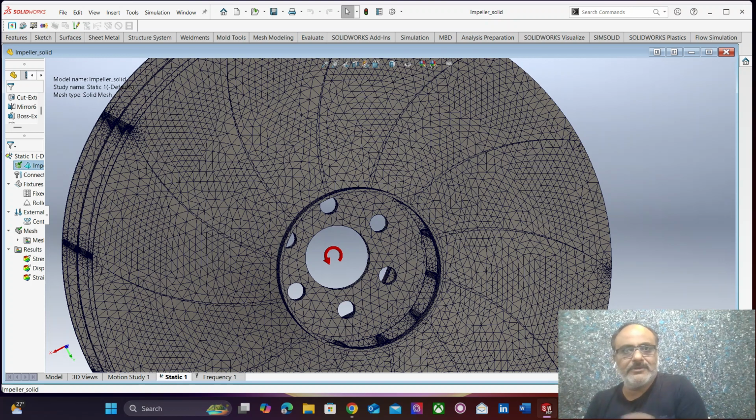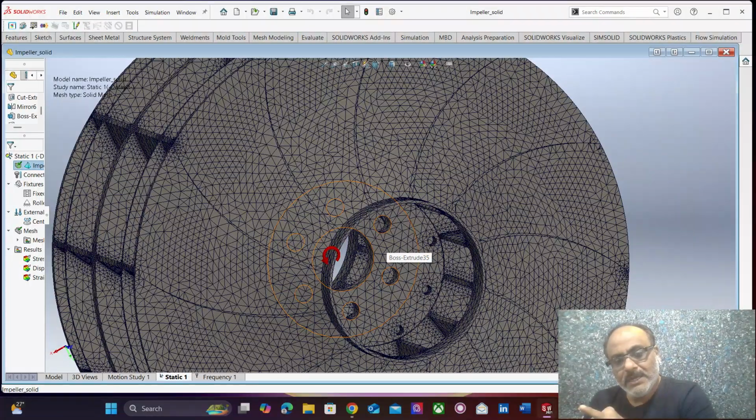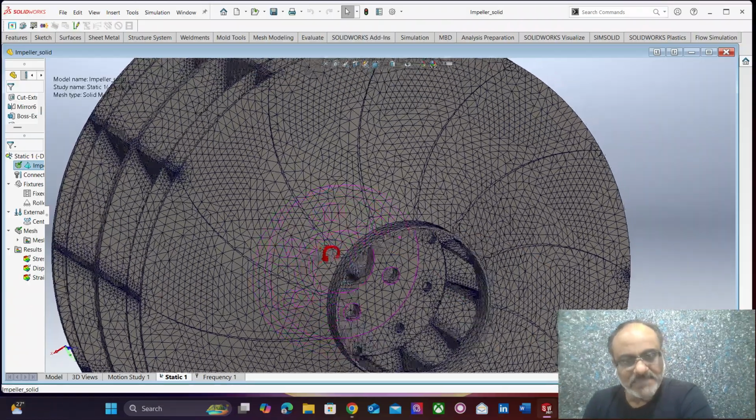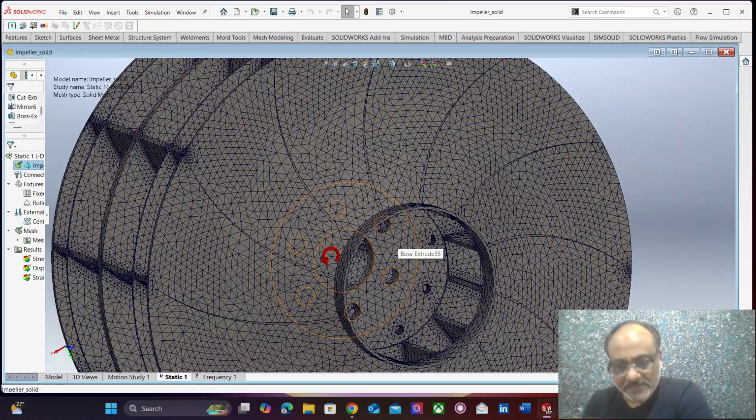So the structure can rotate or the structure can topple, which happens because of the moments. These moments are nothing but the rotations. So here we make the axial part free. The axial rotations are all freely enabled, whereas the translations and the other rotations are constrained.